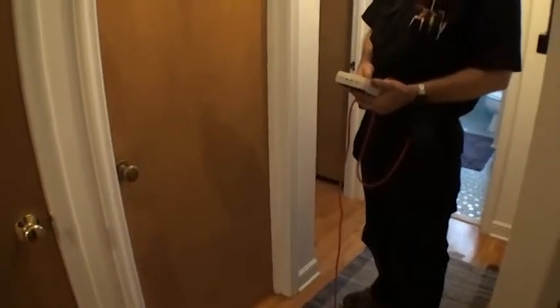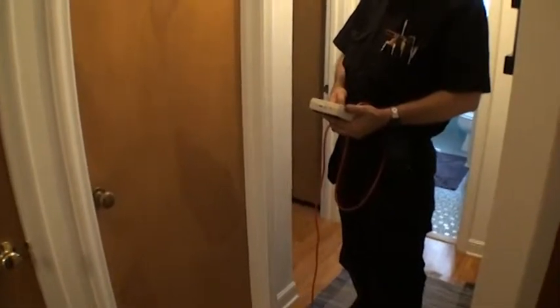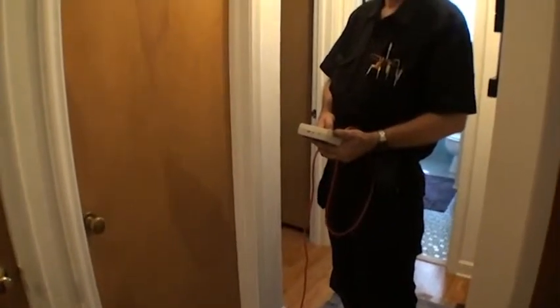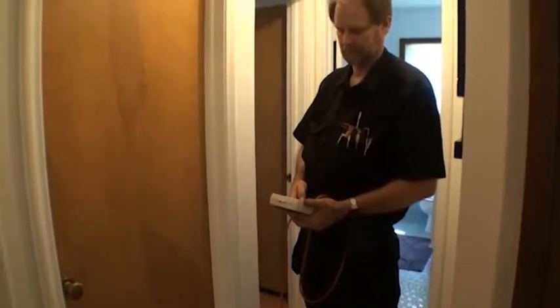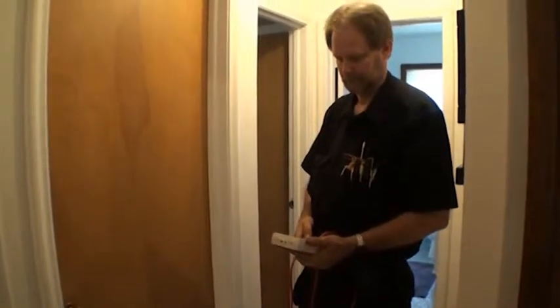Perform room-to-room pressure balancing according to Community Action's step-by-step instructions. This test can be used to figure out where ducts can be added to correct static pressure issues and maintain a balanced duct system. All forced air systems having mechanical work performed must have room-to-room pressure balancing completed.